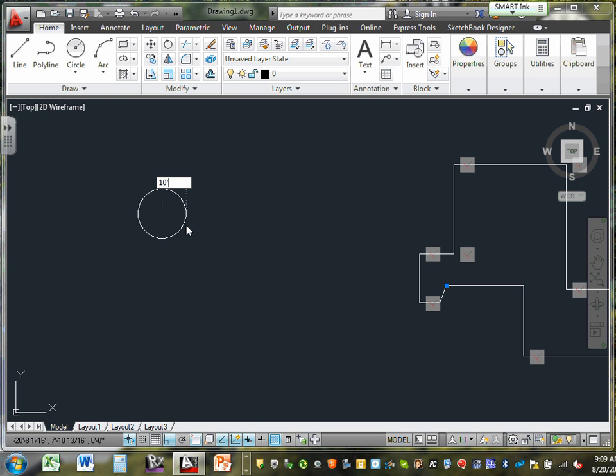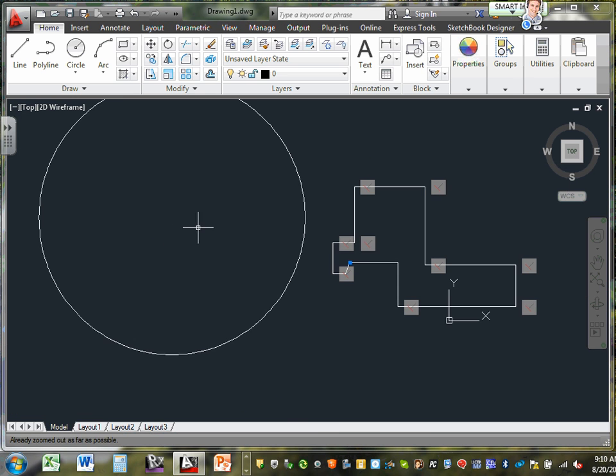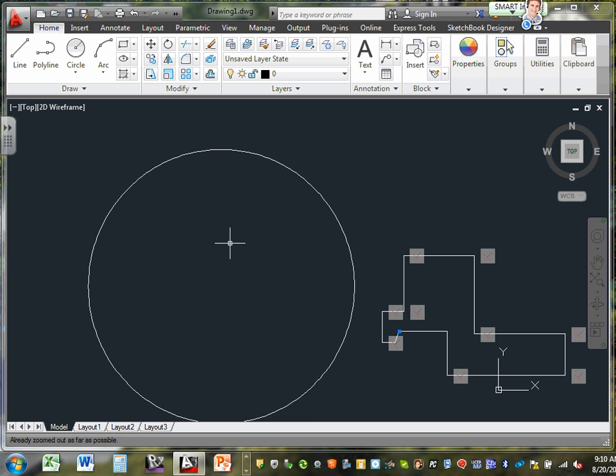By the way, after you put the symbol of the feet, if you type another number, that will be what? When you type the first number with the symbol of a feet, it will be feet. The second number will be inches. So let's type 6, the symbol of the feet, and 6 after that. So 10 feet 6 inches. You got yourself a circle with a radius of 10 feet 6 inches, if you want to draw to scale.